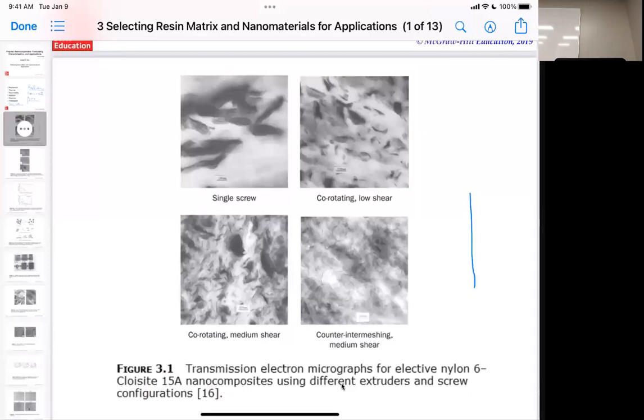In the case of this, where we have Oxide 15, it actually is a quaternary ammonium salt modified natural clay. And so it's spacing the plates out already. And that quaternary ammonium salt, which is compatible with nylon, polyamide, nylon 6 here, it kind of dissolves into the matrix and the polymer takes its place. So the modifier on the nanoparticle is catalyzing with this salt. But we still had to have heat to get everything to move. We still had to have shear to get the tactoids to break apart and not go back.